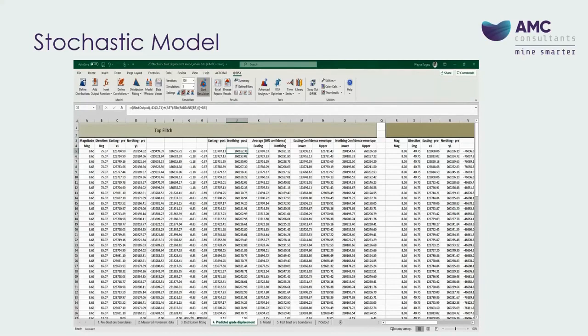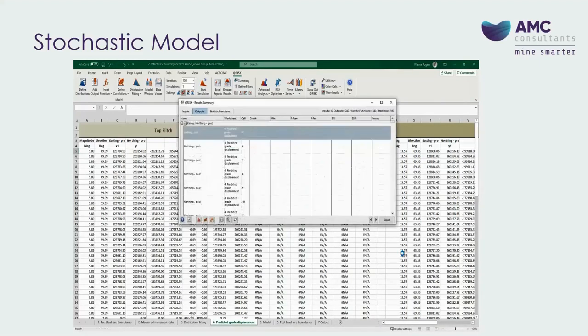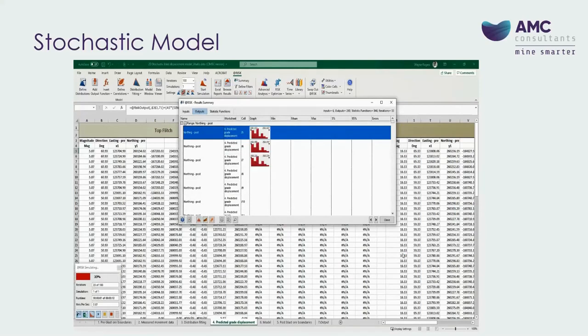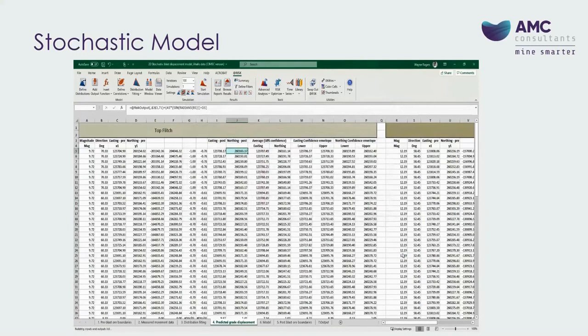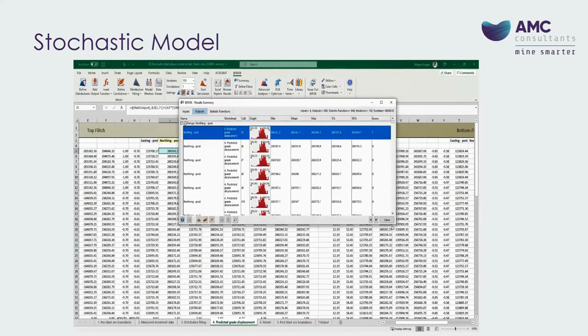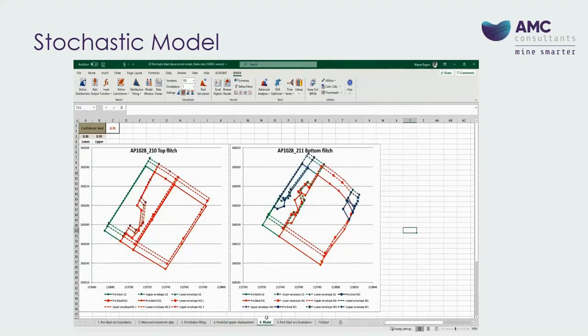So this is currently used at risk, which is just a plug-in for Excel. Monte Carlo simulation. I'm running 100 just for speed here, but you can run up to hundreds to tens of thousands to predict the movement. This is just to show you how quickly it generates the post-blast boundaries. And there we go. So we have the pre-blast and we have the post-blast 80%, or 70%, sorry, in this case, predicted post-blast movement.